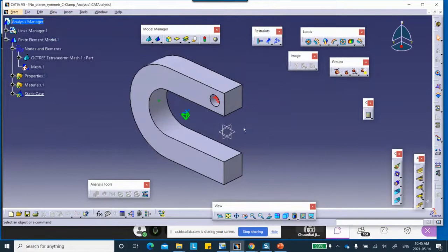Now, how do we push this thing down? If you look at these icons, there is a clamp. No problem. We know what it means. Any point that you clamp does not move for this problem in the direction X, Y, Z. Any node or any point. Surface slider. Whenever you have symmetry, roll, this is a roller. This one is user defined restraint.